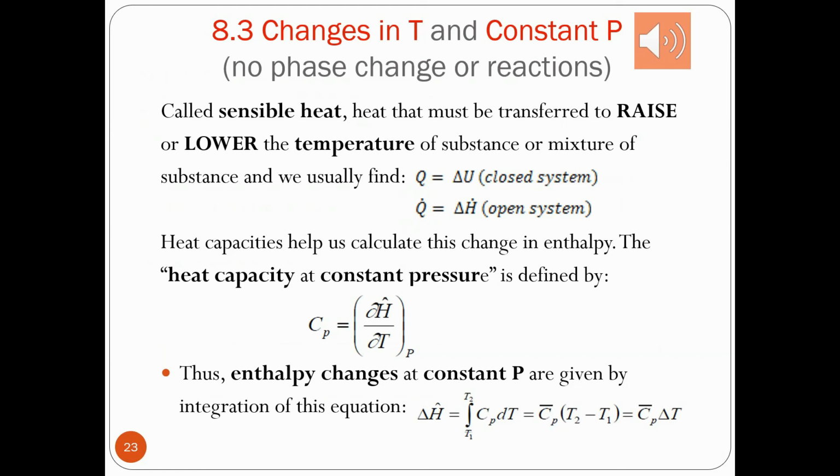This heat is absorbed by the system and the temperature is increased because of this heat supplied. The sensible heat can be calculated from the change of the internal energy or the enthalpy, and this value can be directly used for understanding how much energy, or heat, needs to be supplied to increase the temperature of the system from one point to another.